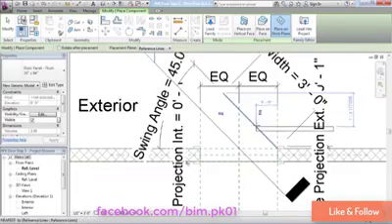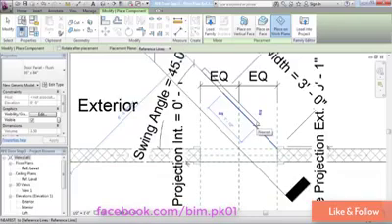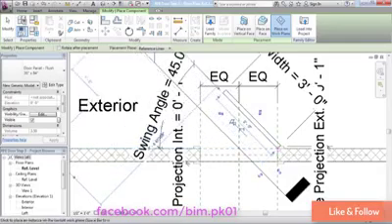If I simply highlight the reference line and tap my space bar, it will rotate to match the orientation of the reference line. I'm going to tap it again, and it will rotate another 90 degrees, and now it's exactly oriented the way I want. And then I can just simply move down here and snap to the end point, like so.